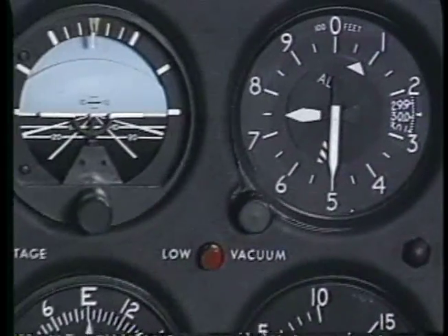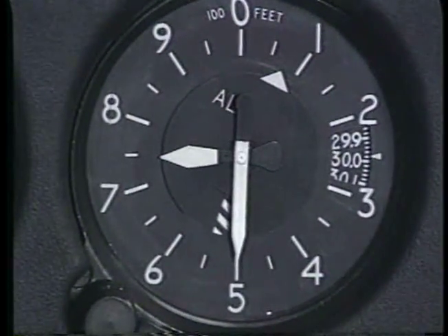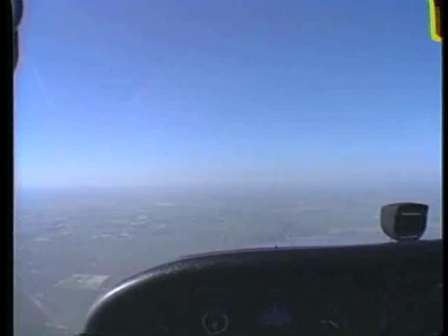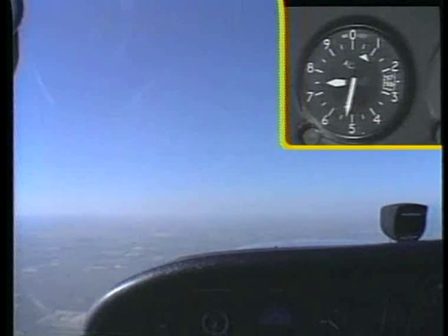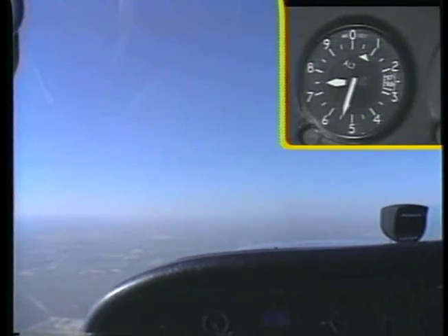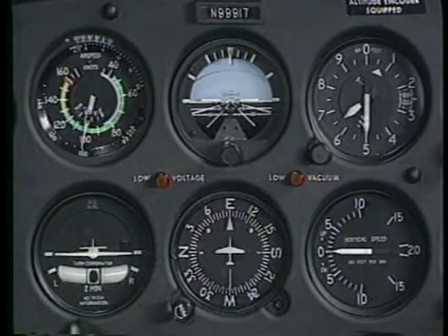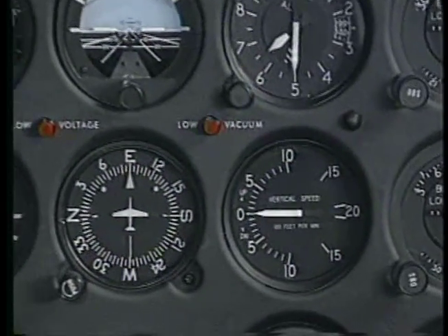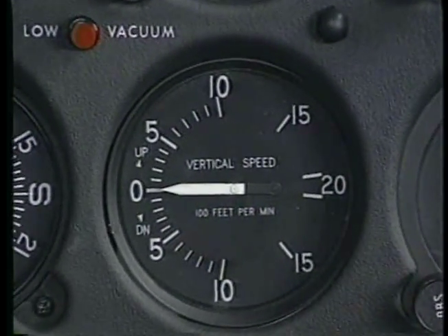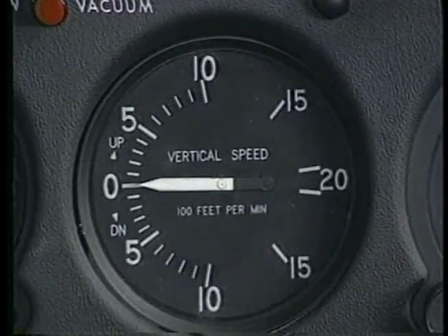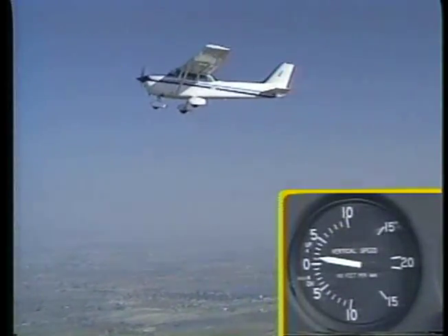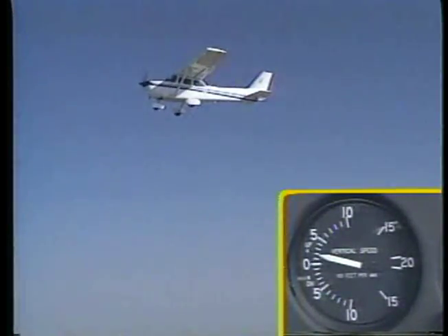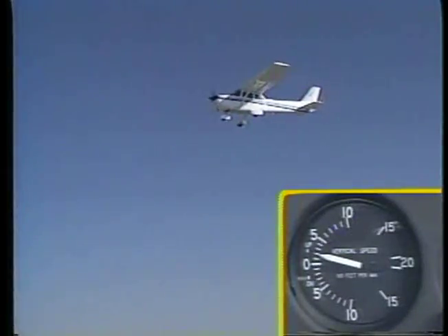The altimeter tells you whether you're at the desired altitude or moving away from it. For example, if your altitude begins to increase due to an inadvertent pitch change or a vertical air current, the altimeter indicates the change. But the altimeter is not the only instrument that tells you the altitude is changing. The vertical speed indicator also helps detect movement from the planned altitude. The VSI instantly indicates the trend of any altitude displacement. The actual rate of climb or descent, however, may take a little longer to register.